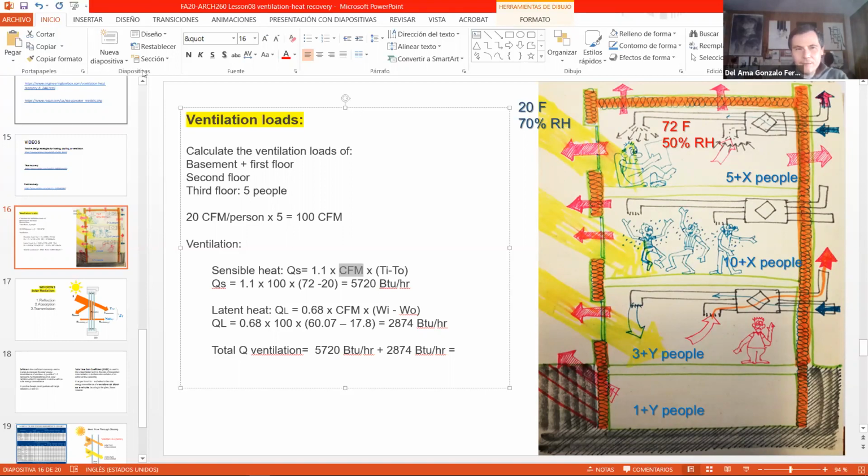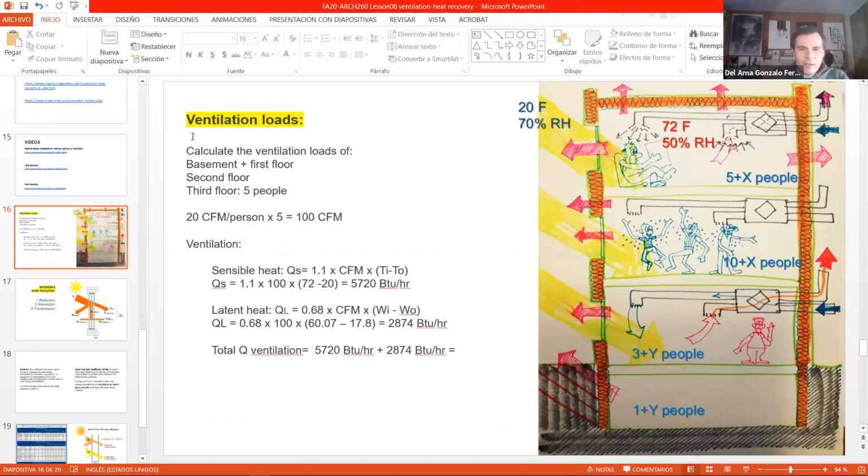Even in single-family houses, because a heat recovery is not just a device that recovers heat. It controls the indoor air quality, because it has filters, so it can remove things that we don't want to breathe. Even getting air from outside, we can have small particles.